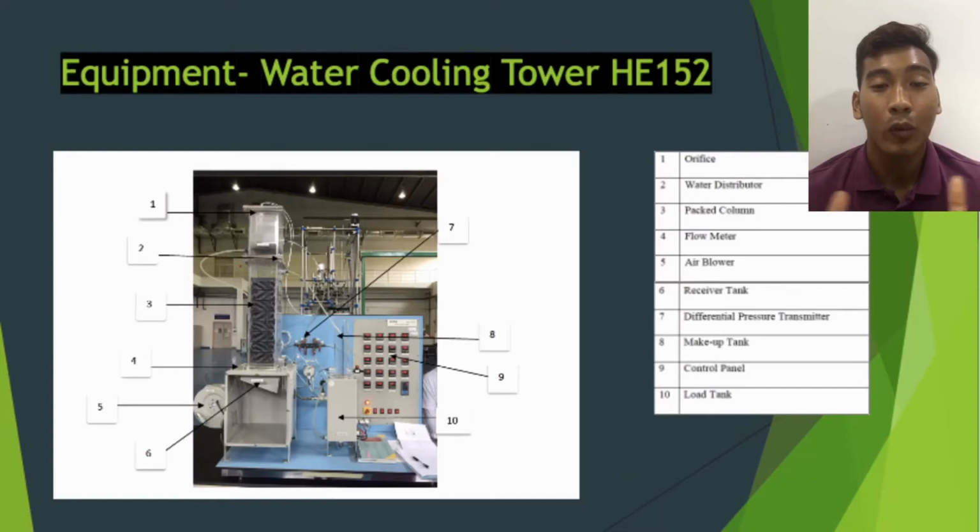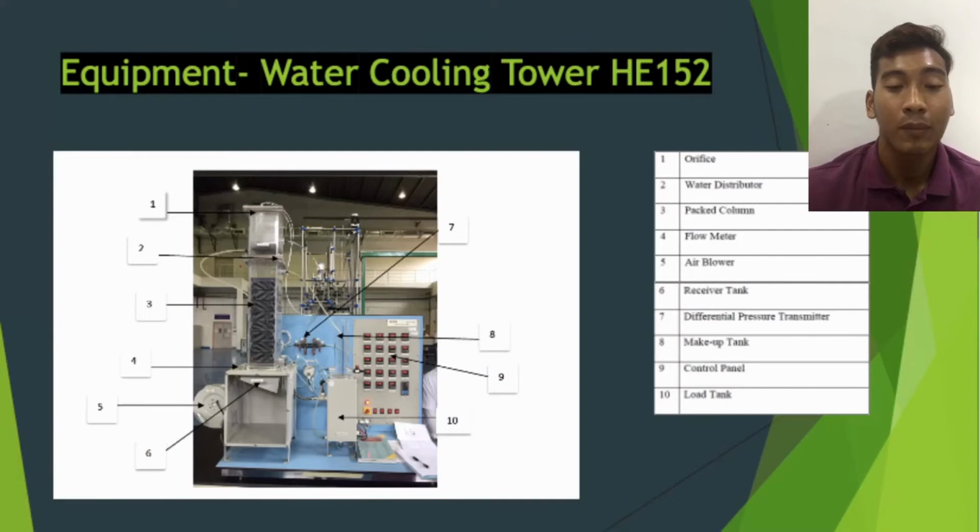The air is blowing as the water flows through the cooling tower. When the air and water meet, a small volume of water evaporates, creating a cooling action. The colder water gets pumped back to the condenser or to the equipment that absorbs heat. The process is repeated over and over again to constantly cool down the heated equipment or the condenser.